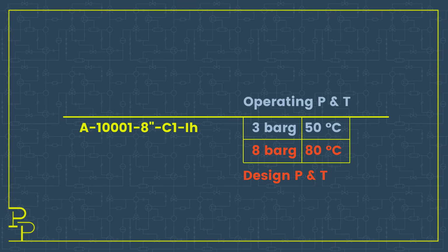So when you're sizing your equipment, you've picked, even though it's the maximum, that's not to say the design. When we talk about design, just like I did at the top of the sheet, there we're referring to the mechanical design, meaning the temperature and pressure that this piece of equipment or this pipeline is constructed to withstand. And that's usually higher than the maximum operating, obviously.